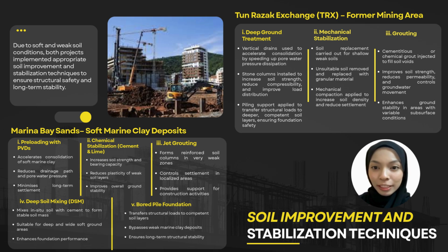For this slide, I will explain the soil improvement and stabilization techniques applied at the project sites, which are Tun Razak Exchange and Marina Bay Sands. At Tun Razak Exchange, which was previously a mining area, the soil condition was soft and unstable because of clay and silt at the project site. Therefore, techniques such as deep ground treatment, mechanical stabilization, and grouting were used to improve soil strength, control ground movement,